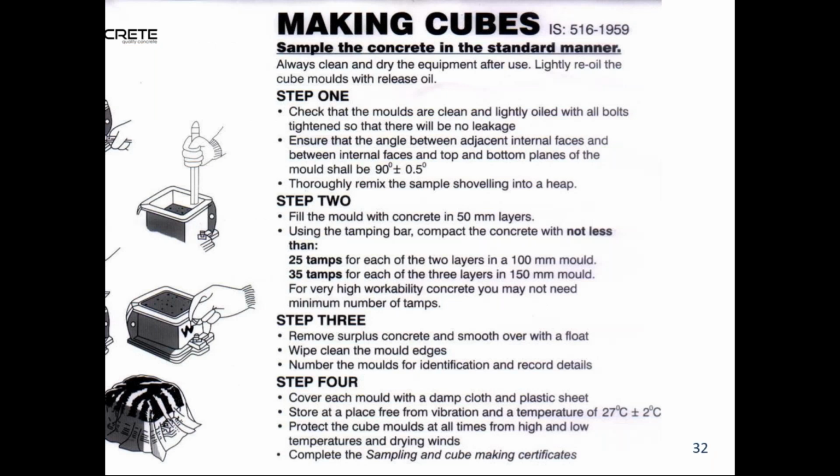So making of cubes has been clearly described in IS 516. Very, very important actually. So here trained technicians have to be used. Trained technicians have to be used. 35 strokes each layer.